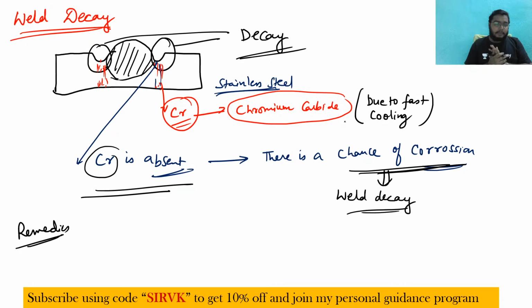The temperature was not uniform. Definitely, if the temperature would have been uniform, then there would not have been a fast rate of cooling. So what we can do is provide preheating and post heating.